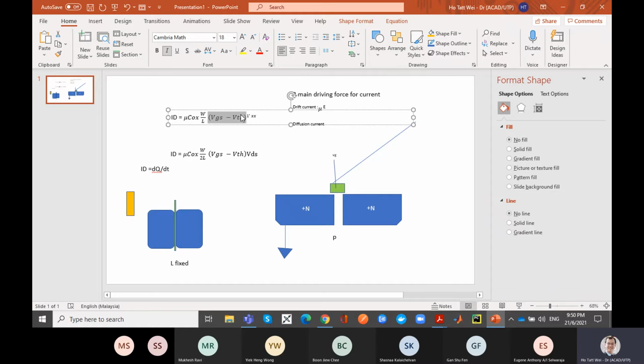So the sensitivity of VTH will change your speed sort of linearly, sublinearly around there, but it will change your leakage current, the power that you are losing over time, which is the most important parameter for embedded devices, by many multiples: factor of 2, factor of 3, factor of 4. Big change. That's why process variation is the enemy of all these low power devices. You got it?